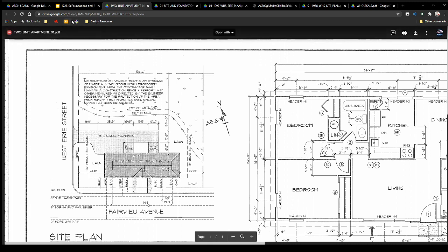And so the setbacks are going to be different based on different local codes or maybe different features. If there's a river running through the property, you can't build within a certain amount of feet of that. If it was construction in a more urban area, then the setbacks would be reduced because space is limited there and you need to build in whatever amount you can.